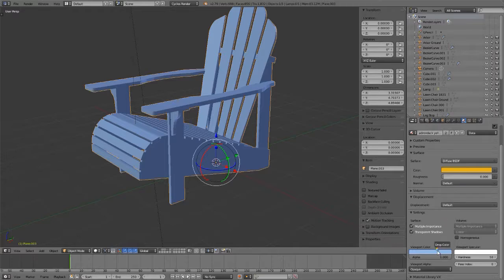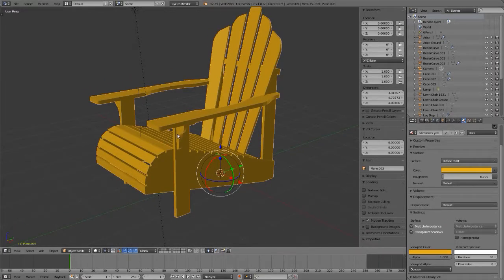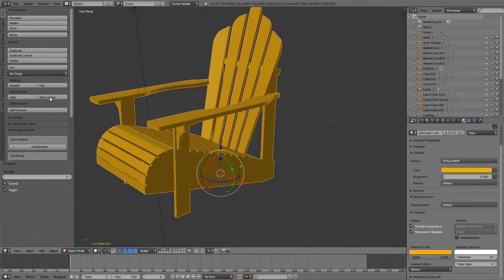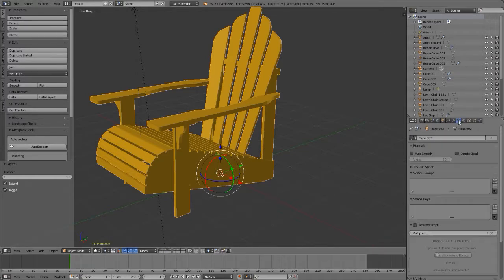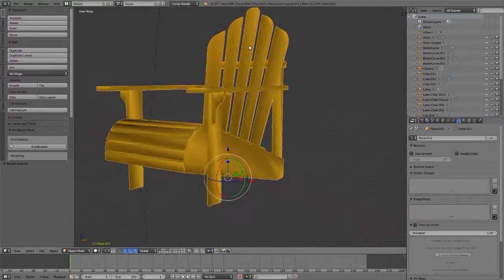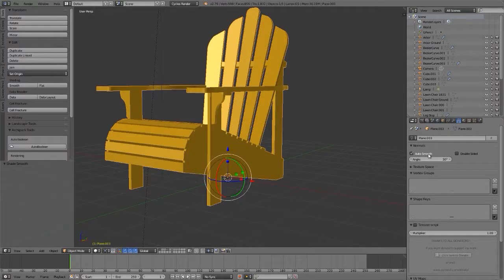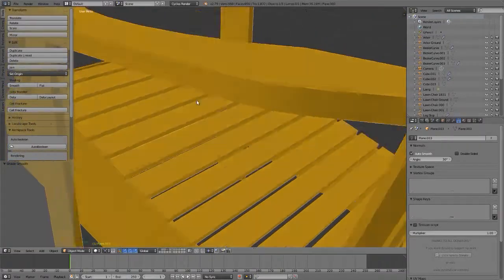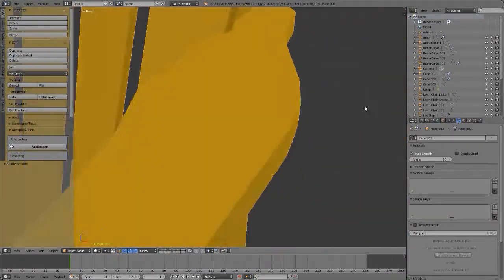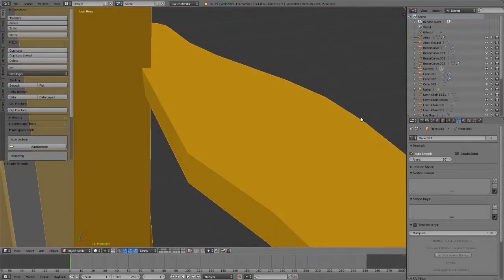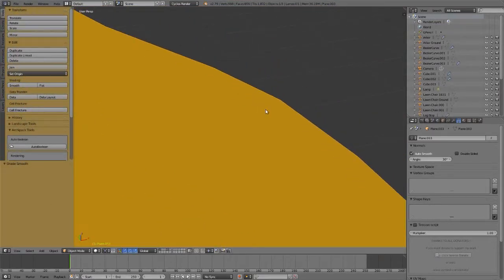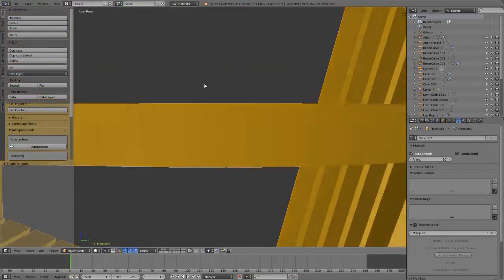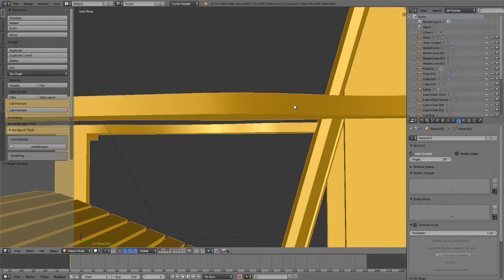Press N to hide that, and T to do this. And look at your object data, which is mesh object data. When we smooth this, nightmares happen. But when we auto smooth it, fewer nightmares happen. This piece was a real challenge because we deleted certain vertices and edges to make grid fill happy. So while you can see a pretty tough profile if you're close along the grazing angle of an edge, the facing angle of that same edge is smooth. Those are real words, and so if you understood that, good.